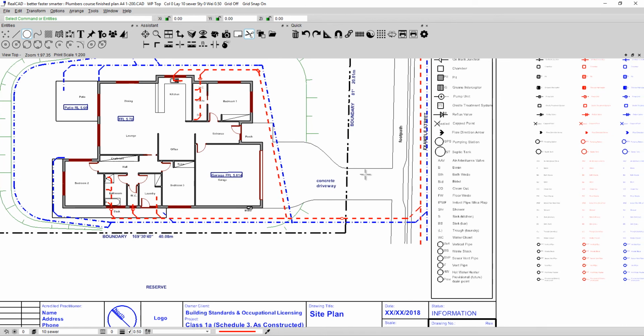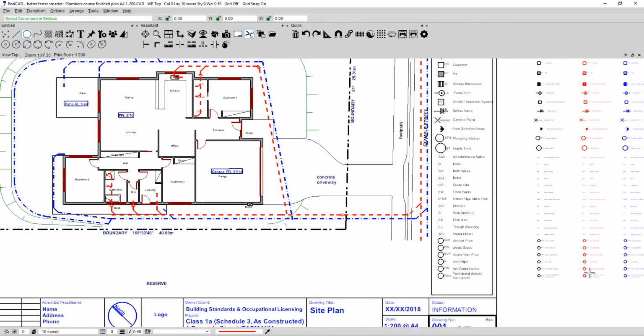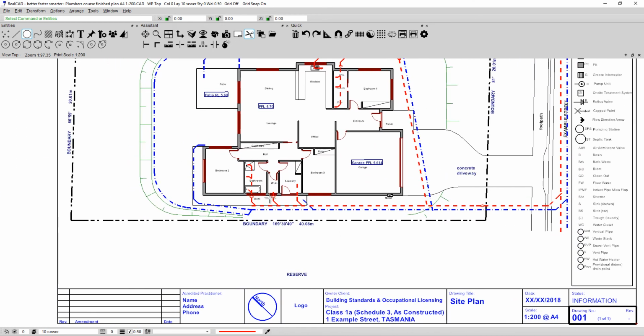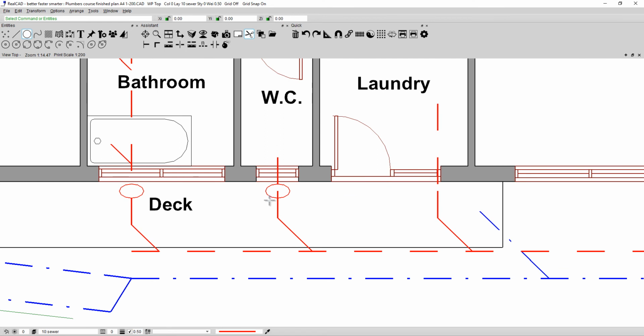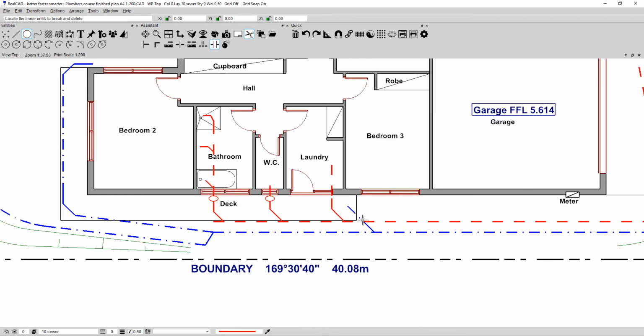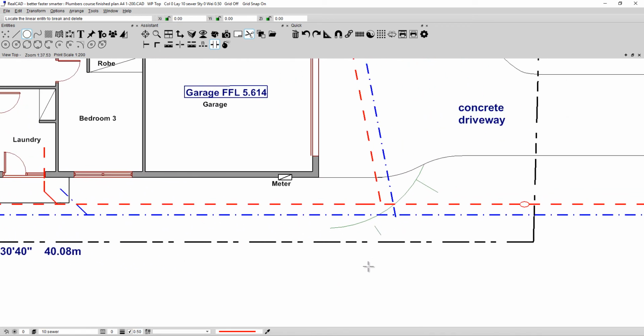So we could just use one of the circles from here and repeat it, or we could draw a circle. It doesn't actually matter. They are literally nothing more than circles. Oh, and we haven't chopped this out yet. Let's complete this process of trimming. This one looks like it's trimmed, but that line still passes through. So if you recall, that really does need to be chopped. So select the tool, select the line, trim between here and here, select the tool, select the line between those two. Very, very neat end result will come from this.